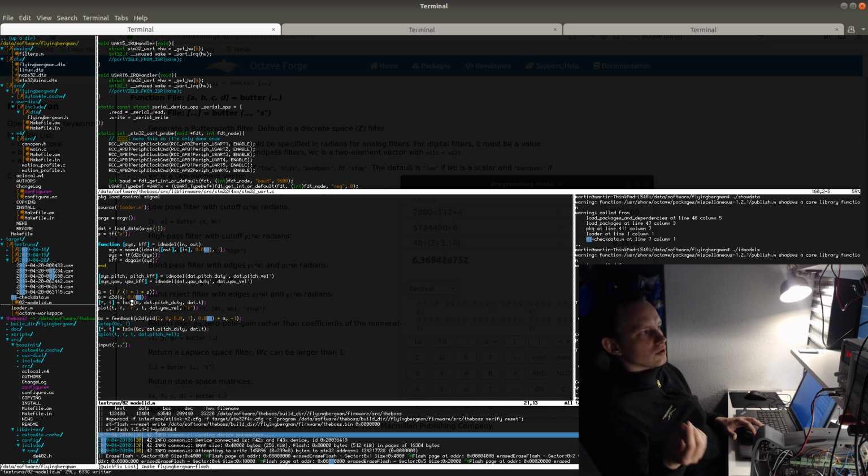When designing controllers, it's important to know what quantity you should measure. What quantity directly translates into the quantity that you're trying to control? In this case, we're trying to control the velocity, so we need to know the voltage on the windings. We can assume the voltage to be proportional to the duty cycle times the DC line voltage of the motor.